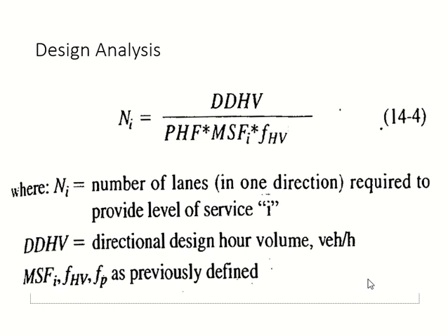Okay, in level of service A, that means you are in free flow. And this is what DDHV is, your design value, and as you said, design is for peak hour, right? So in peak hour, if you are in free flow conditions, that means you have overestimated your design, right? Imagine you have 20,000-30,000 vehicles in the hour and you are still in free flow conditions. That means you have overestimated the design.